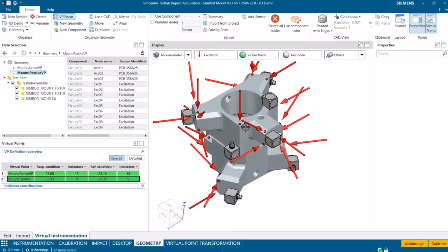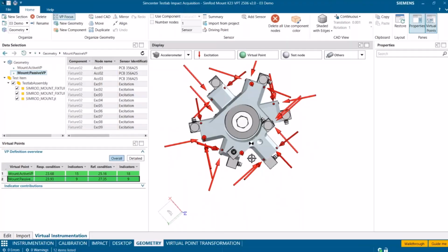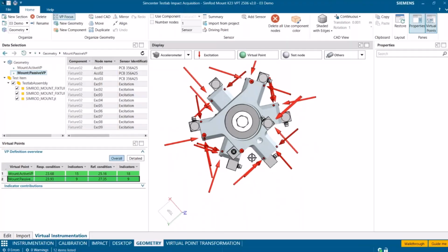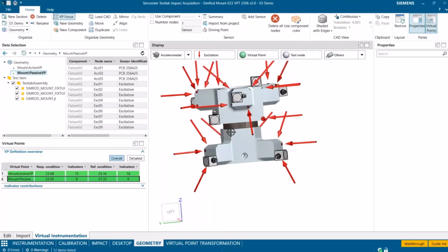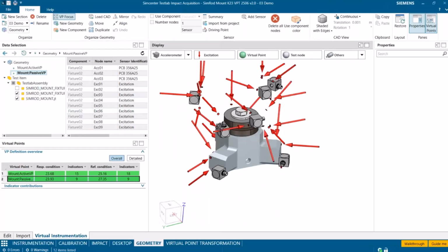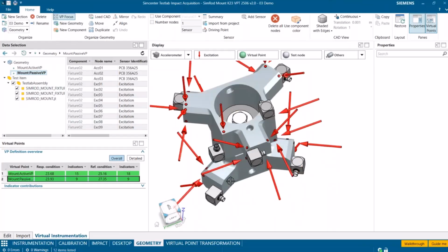And these jigs are something that we manufacture ourselves in our workshop. So this is something that we typically optimize in CAE where possible, to find some geometry that gives us the highest rigidity. So the highest frequency for the first bending modes is something that we optimize in CAE. And then we manufacture them in our workshop because they need to fit exactly on the geometry of the mounts that we want to measure.